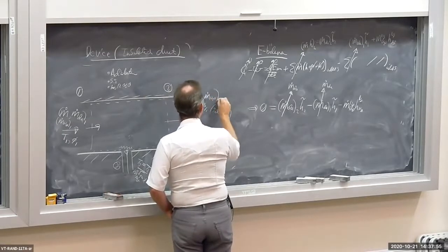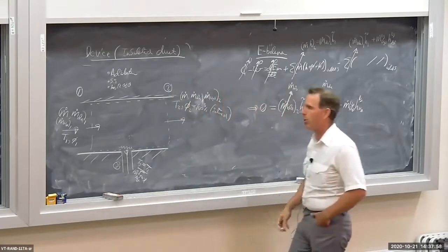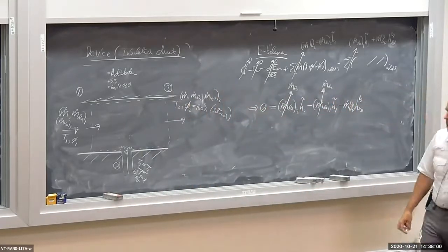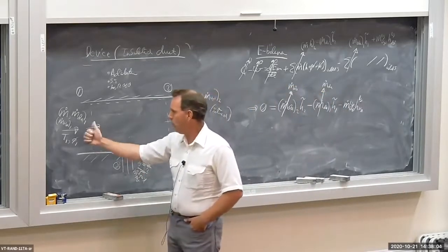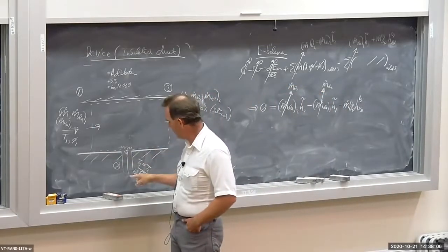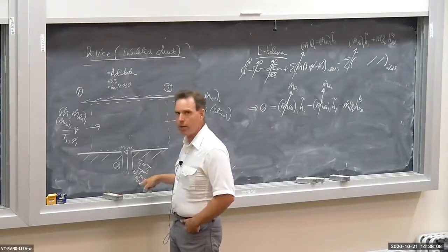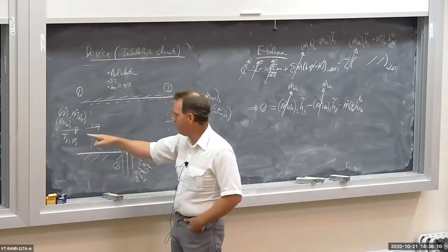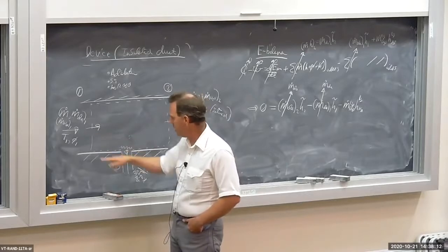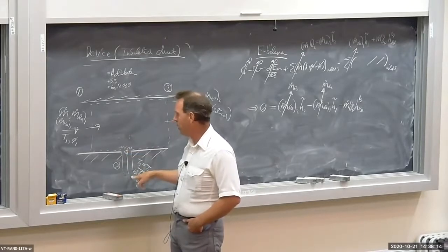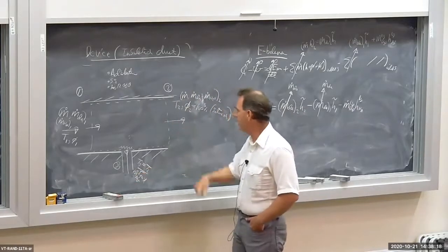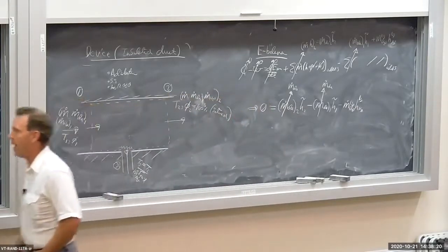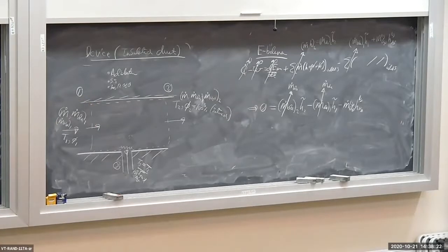It's moist air flowing out. So there's an m dot H2O out as well, okay? So I have one inlet here where H2O is flowing in. I also have another inlet here. It's my m dot liquid water. So I got m dot H2O at the inlet, m dot liquid H2O at this inlet, and I have one outlet, m dot H2O at the exit or location 2.